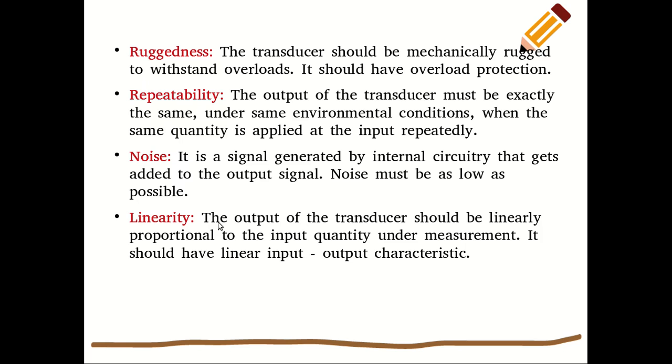Linearity of transducer. What is meant by linearity? It is the output of the transducer in comparison to the input signals. So what we expect is that input and output quantities should be linear to each other. So we can say there should be a linear input output characteristic.